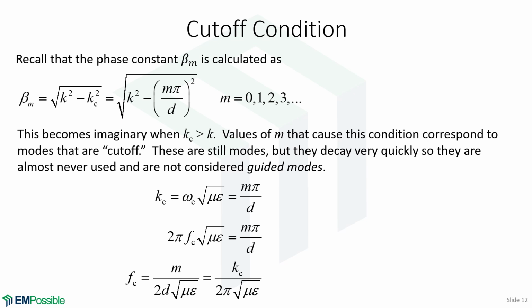And so we can take this now and solve for cutoff frequency. And long story short, we have the exact same expression we had for the cutoff frequencies for the TE modes. This is really good because we can just use the one equation and calculate cutoff frequencies for both TE and TM at the same time.